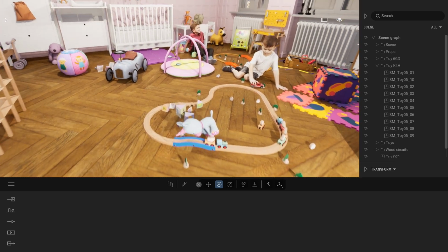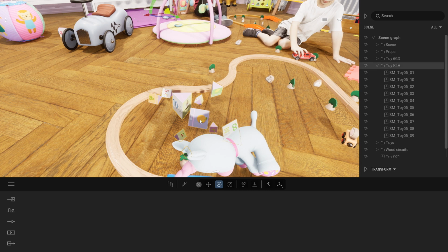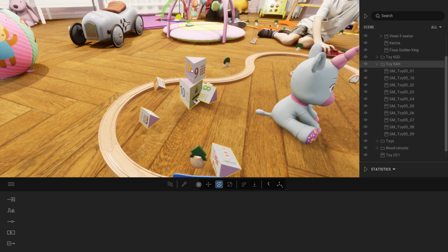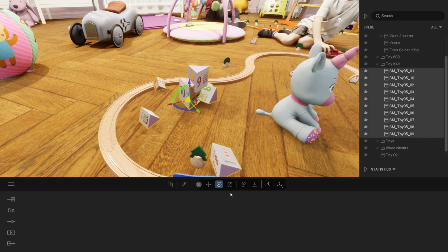When activating the physics, make sure to not have objects that intersect each other. So for example here, if I move that object inside that other one, now let's select the two and press the physics, they will just move away from each other. That could result in some strange behavior from time to time. Here, same idea, if I just move one inside the other, when pressing the physics, it will just bounce and sometimes just explode.